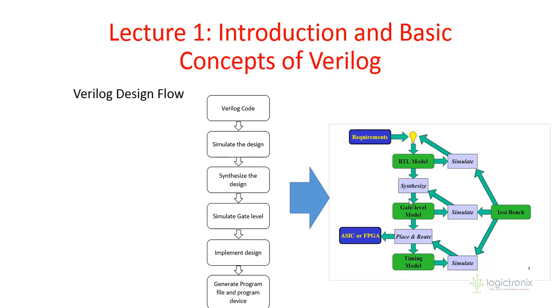And after that we have synthesis, gate level modeling, again simulation. Simulation actually utilizes the test bench. Basically, a test bench is a program or code for simulation, like the normal Verilog program for simulation is the test bench. Then after the synthesis simulation, we have place and route, timing modeling, timing analysis, again simulation, and we can go for ASIC or FPGA. So this is the Verilog design flow, which is followed on the overall design of projects or verification steps for VLSI as well as FPGA.